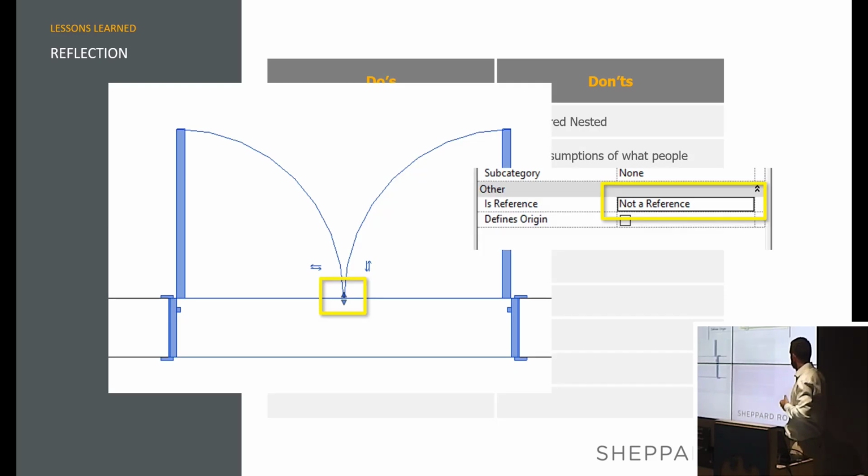So another issue as well is if you have instance parameters, length parameters, and you load them into your project and they're controlled by formulas and bits and pieces. Sometimes you do get the grip inside your project, and you'll always get one smart guy who says, "Oh, what does this do?" Pull it, and then it breaks your family.